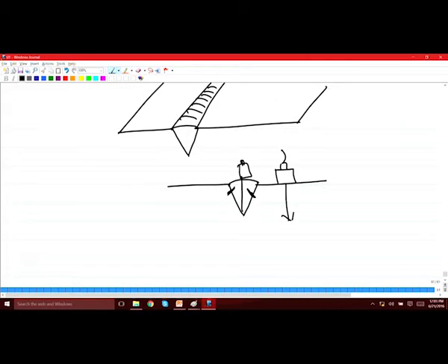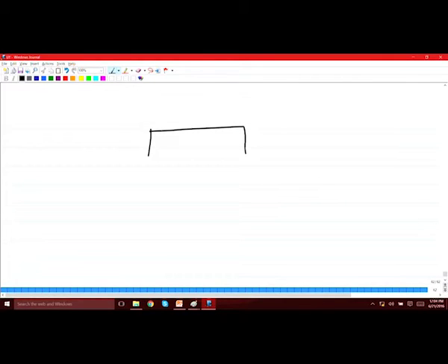Okay. So, what we need to do in this case, we need to use an angle probe, so that you would be able to inspect these surfaces like this. Okay. So, when you have a scenario like this, where it is sent at a particular angle, what is going to happen is this is going to reflect back and forth like this. So, first it will reflect from the back wall, and then it again goes to the top surface, and then again comes back like this, and so on.